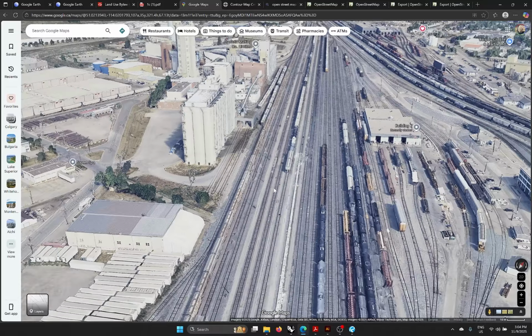So after you've checked that, you just need to drag these to the same spots that you had your originally defined area. So once I'm happy with that, you just want to leave the scale alone and click download. So this is going to download a PDF file of the OSM map region, and then I'm going to just simply drag this into my Rhino space.